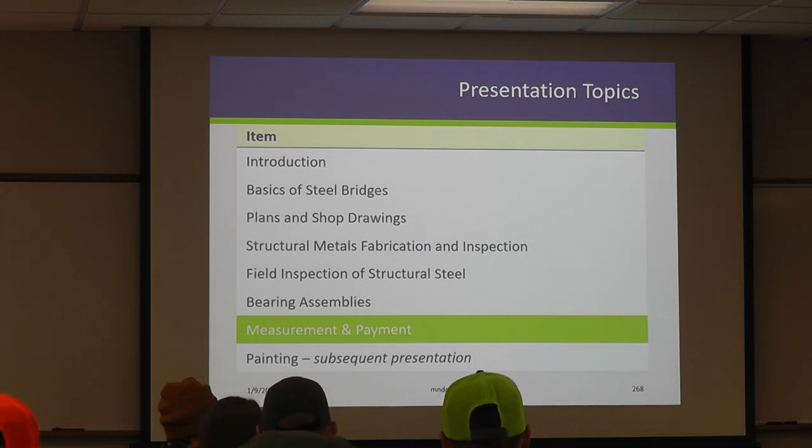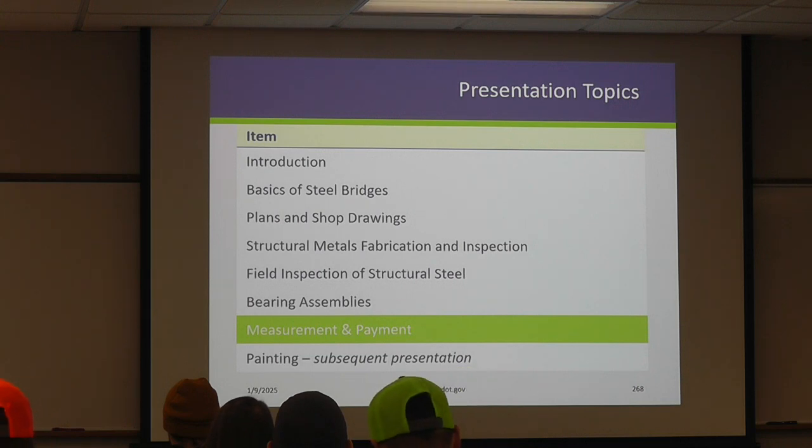Because I do a lot with our maintenance forces too, sometimes the loads get so light on these things that those elastomeric pads will walk around, either because they get really stiff when the weather gets cold, or there's enough vibration where they'll wiggle around. So we put these little keepers on the bottom of our standard bearings now to at least force everything to go along. But we do have them walk out on us. I've been out on sites where the pads are laying on the ground, the beams being held up by the deck. Ideally, you catch that before really heavy load hits.